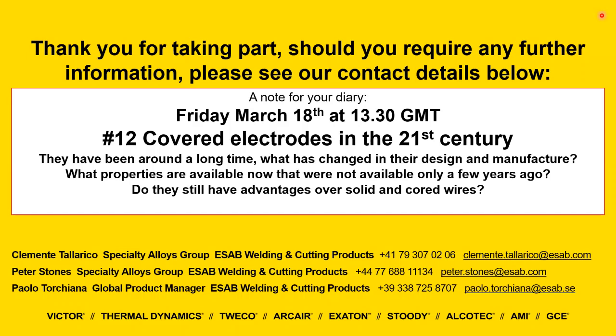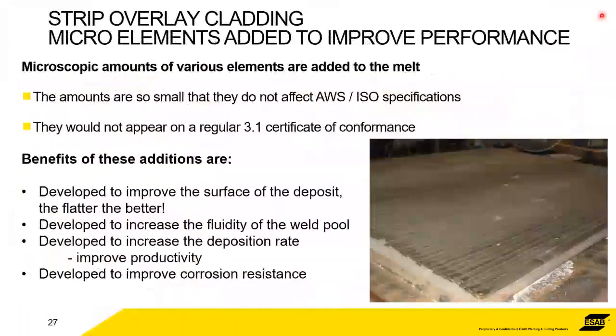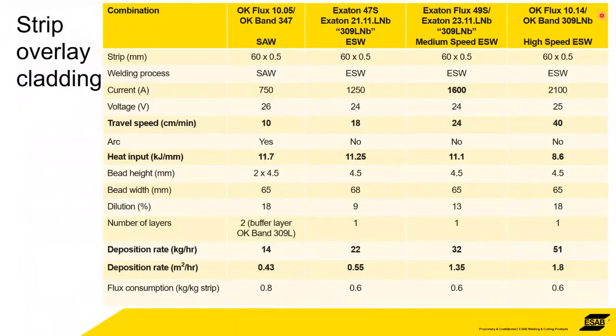It makes sense. 1200 amperes. It's enough. Important is that we have a duty cycle of 100% in that case, but for sure, if it is not a 60 mm strip, a 30 millimeter strip can be welded. Yes, that's exactly what I was going to say.